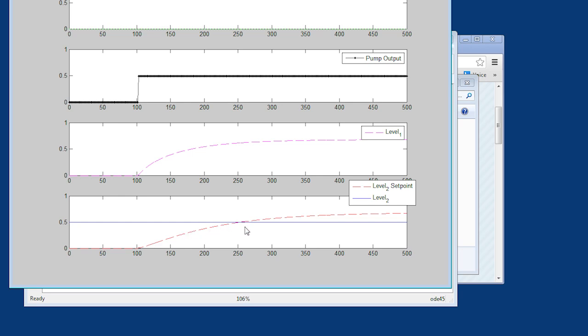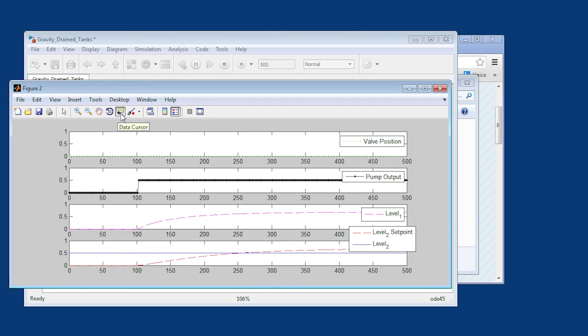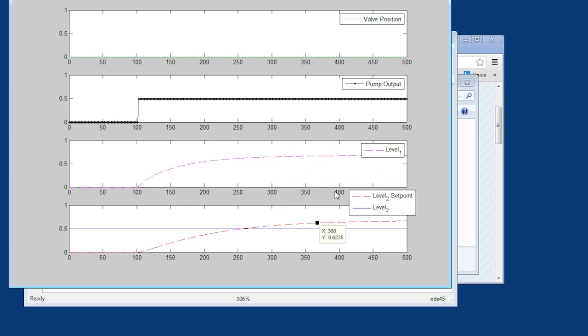when you see the initial response. And then the first thing we need to do is determine the final steady state value, so I'm going to use my little tracer tool here. Right at the top there's a little data cursor. And if I go ahead and select, I can see the actual value. So what I'm going to do is go ahead and trace it along this plot here, and just figure out what the final steady state value appeared to be.